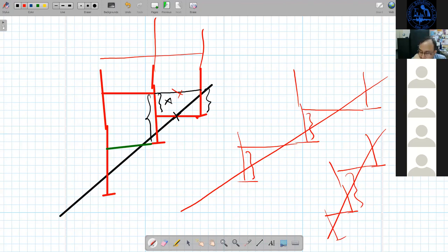That's it. There will be the possibility of formation of plastic hinging in that short column, at the upper side. And the short column will fail in shear. We want to avoid failure of the columns in shear. To avoid that short column effect, can we provide the shear wall in the direction of the slope?